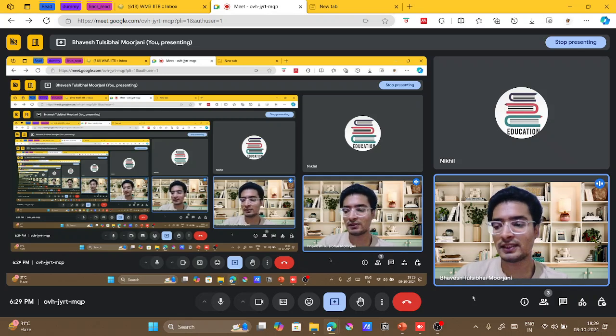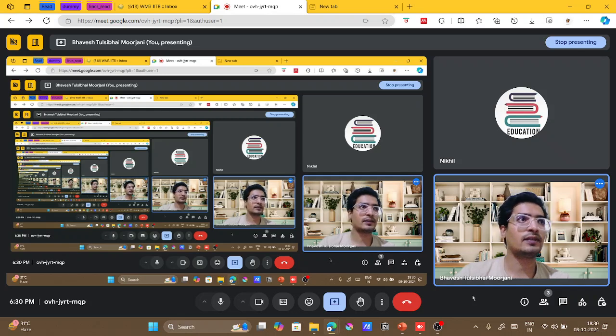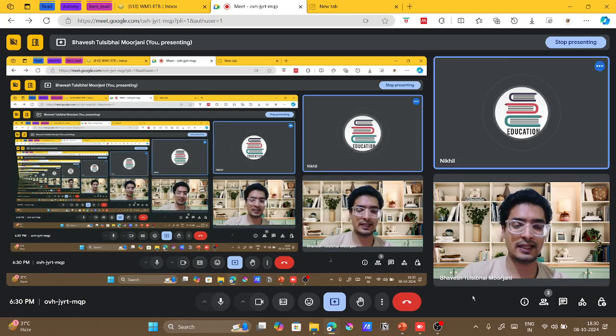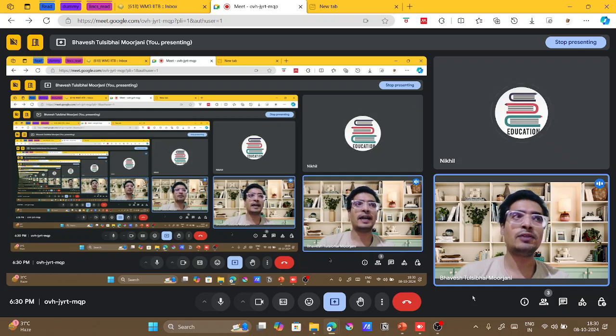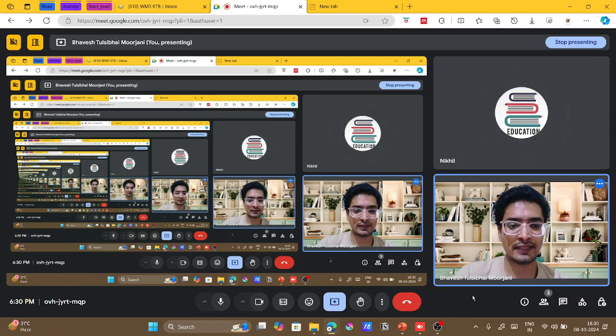Second reason could be, which I was saying initially, that it might be difficult to separate the inert. It might become a costly thing. So in that case, you don't bother about separating the inert. Let's say nitrogen and oxygen, air mixture. So you have oxygen, nitrogen, some argon and some smaller components present. In that case, if nitrogen is not taking part in the reaction, why separate nitrogen and oxygen? It will add to your cost, right? So that's why you don't separate it.